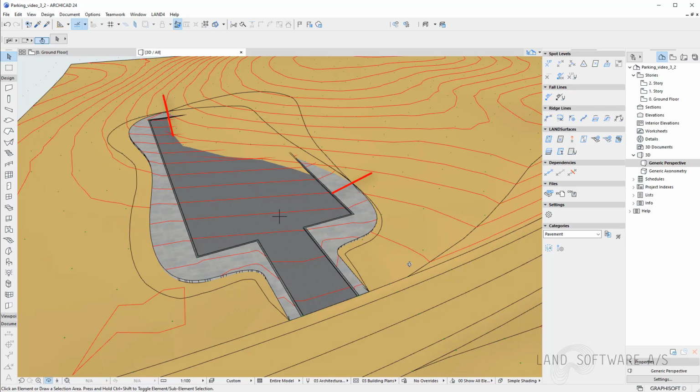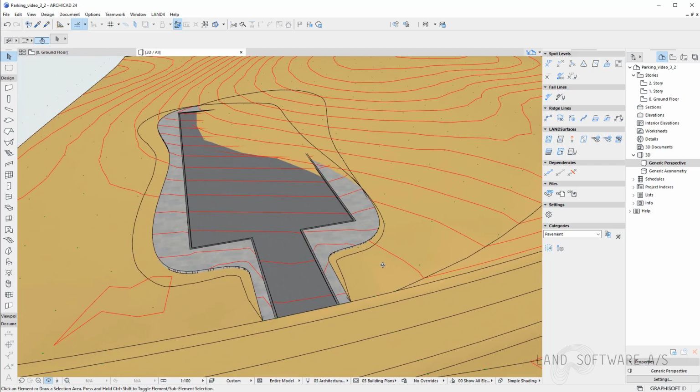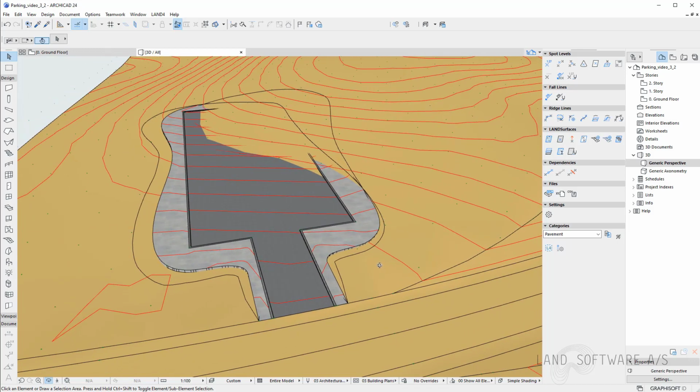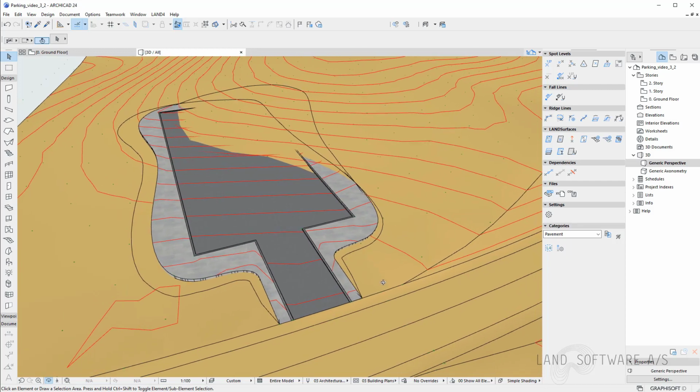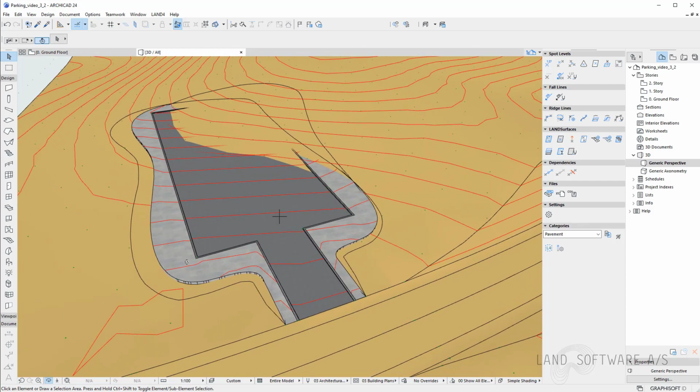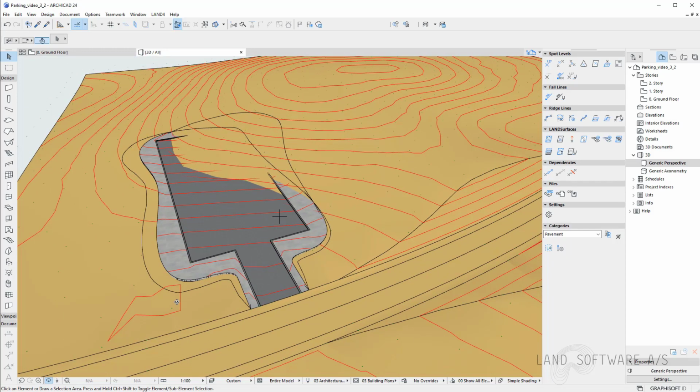That's where it intersects the constructed surface, basically. Last but not least, we have control over the fall percentage when projecting these lines. So we can have different fall percentages on each side of the constructed site. Therefore, we can control the balances of the cut and the fill.